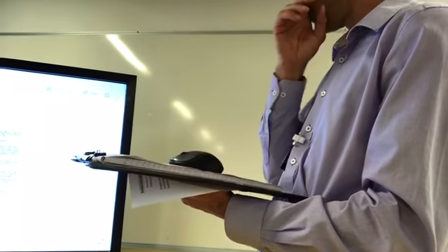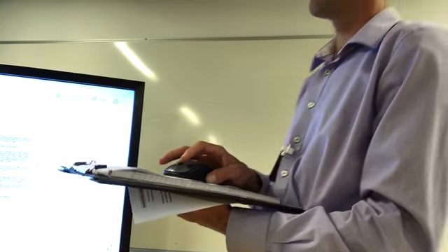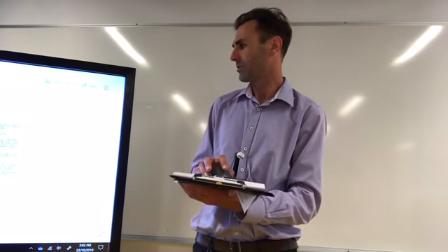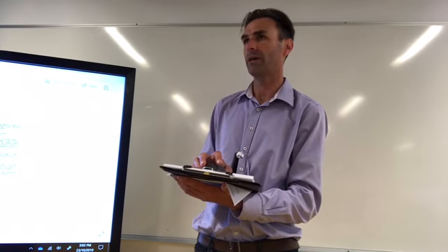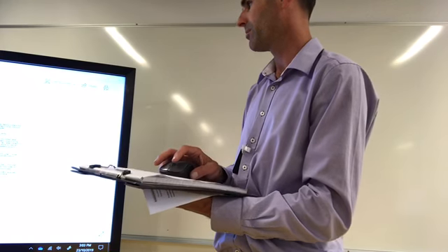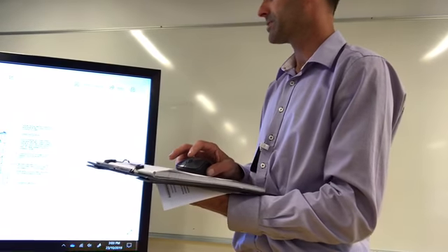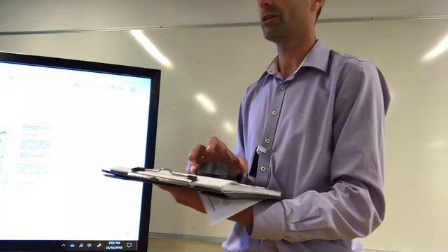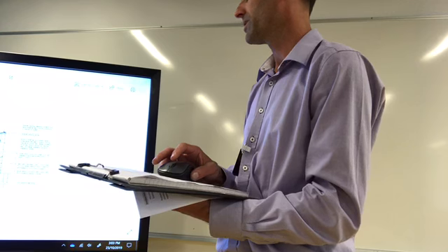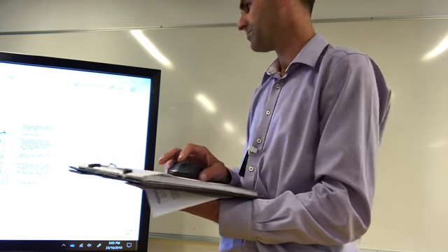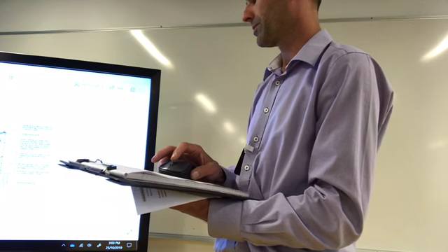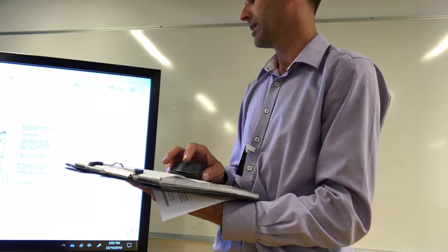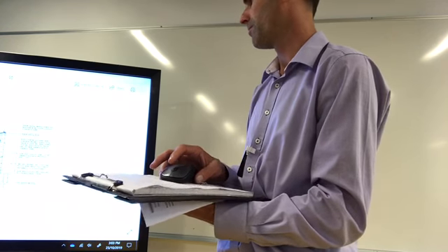So we're working through that. We've determined our box gutter size, determined our rainwater head size, and now also determined our downpipe size. Other aspects we're going to have to include: we're going to have to specify some sheeting and slope of your sheeting. The rest of this can be indicative, including the ceiling system underneath. You'll want to include some indicative insulation in there as well.